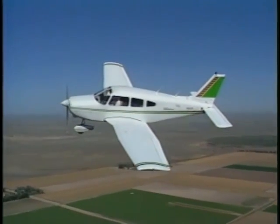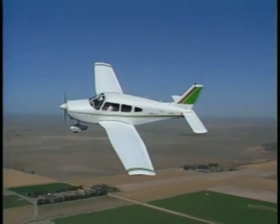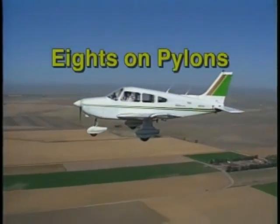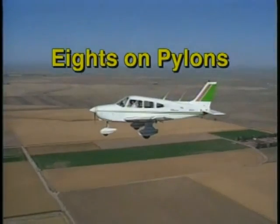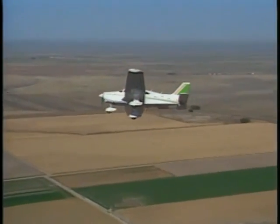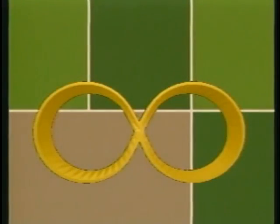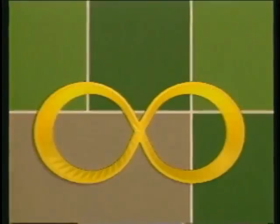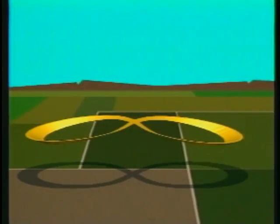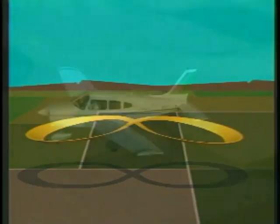Another ground reference procedure that involves flying in a figure 8 pattern around 2 points on the ground is the 8s on pylons. During 8s on pylons, you don't maintain a uniform radius around the pylons, nor do you try to maintain a constant altitude. Instead, your goal is to vary your altitude and airspeed to keep a reference point, usually located near the wingtip, on the pylons.